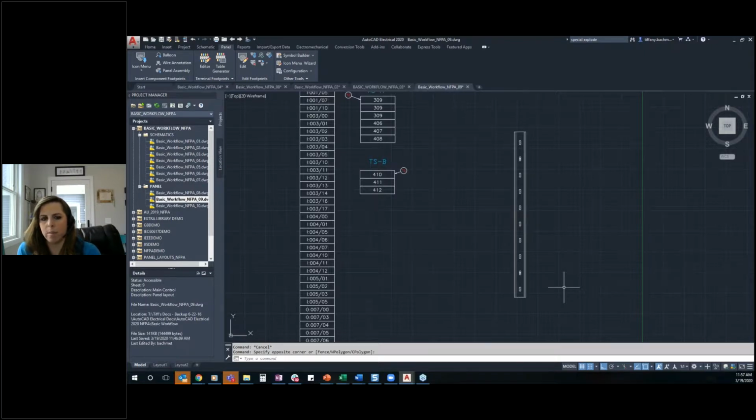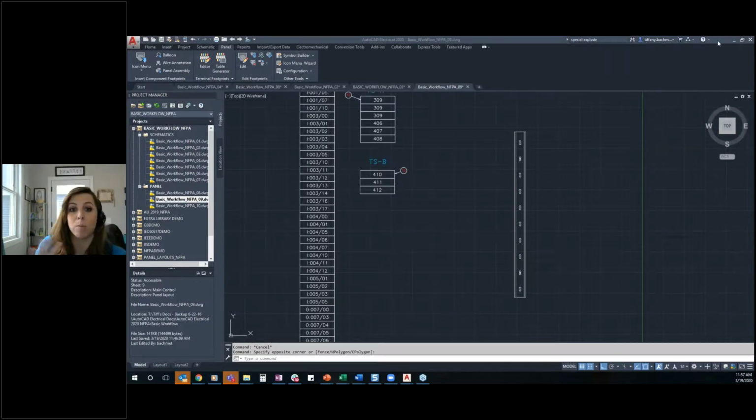I thought that this Allen Bradley one actually had that stretch capability, and obviously you saw that it wasn't going to let me do that without exploding it. And if any of you have taken a class from me ever, you'll know exploding is a terrible, terrible word to me, because you do not want to explode your DIN rails, because now it's not going to show up in your catalog list. So my advice is, if you think that you're going to need to be stretching and rechanging sizes of them a lot afterwards, turn these into dynamic blocks that allow for that stretch. If that's not something you typically do, then they're fine how they are, and just draw them at the lengths that you need, especially if you're doing bracket pieces of them that you want to break off.